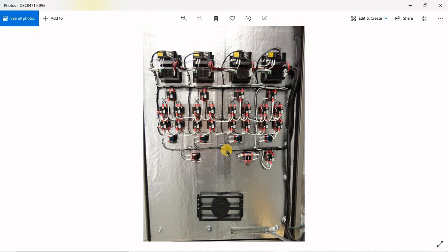This is an actual case when we already placed an order with a turbine manufacturer, one of those great turbine manufacturers, and we gave them an order of more than $20 million of cabinets and turbines, but their standard is to use all wire inside the cabinet as gray, so they don't use black and white. Maybe only the 24 volt power supply is red and black, but all the other cabinet wiring should be gray. If you try to change them, they will not deviate from that, because they have not only your cabinet, but they have a standard cabinet.